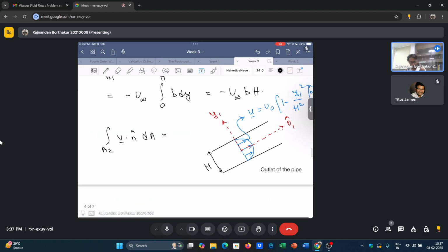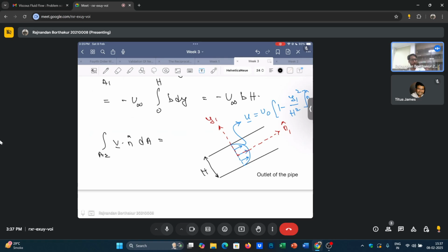The only difference that you can see here with respect to the inlet section, as I have said repeatedly, is that the velocity profile, instead of being just a constant, is actually a parabolic profile, which is a more realistic scenario of what actually happens inside flow through pipes. Basically, in a viscous fluid, you don't typically encounter uniform flows, because you get the no slip boundary condition at the walls. So because of the presence of viscosity, you tend to see a parabolic profile of this form. Okay, I hope this is clear.